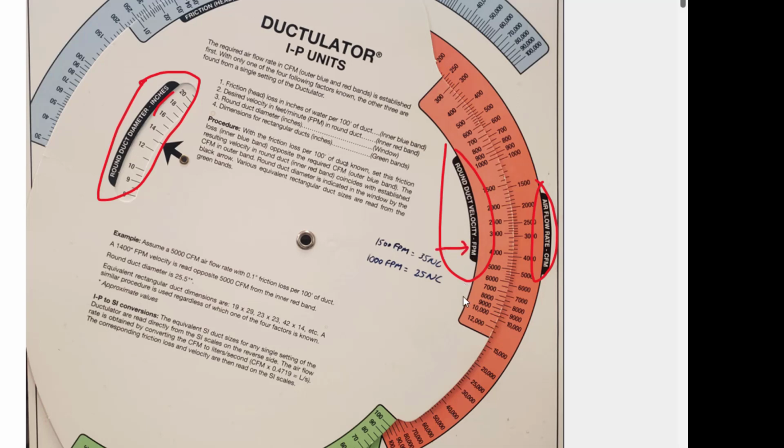FPM. And you generally want to size the duct so the feet per minute do not exceed roughly somewhere in between these two numbers. So generally for residential, you want to keep the NC level at about 30, no more than 30. So 30 falls right in between these two numbers here, the 35 and 25, which should fall somewhere in between the 1500 and the 1000.